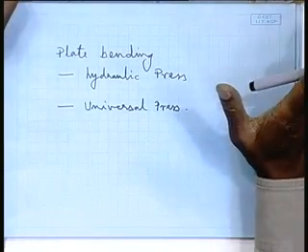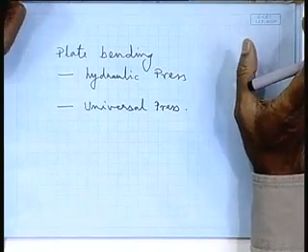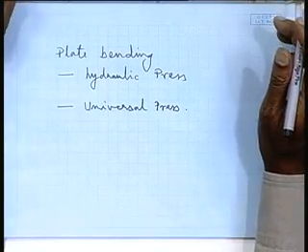Okay, continuing with plate and section forming, we have seen how we go about bending frames, talked about plate bending, and we have seen that if it is a developable surface, that means with a single curvature like cylinder or cone, the example we saw is the bilge plate of a ship.